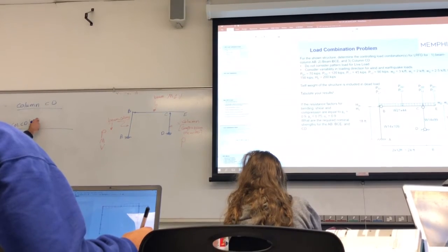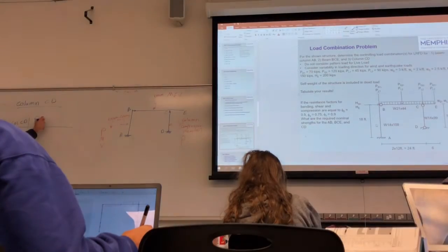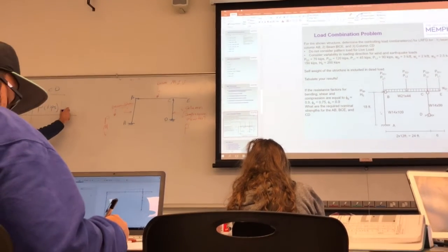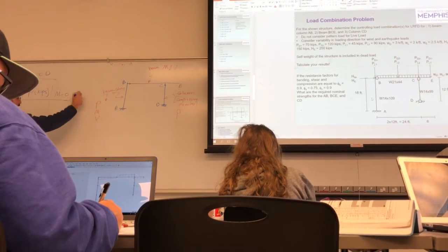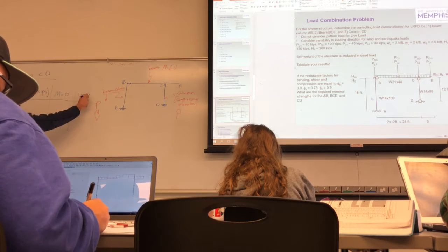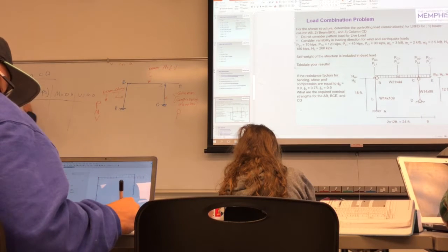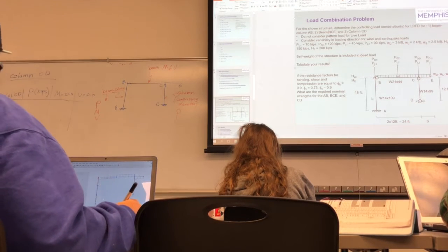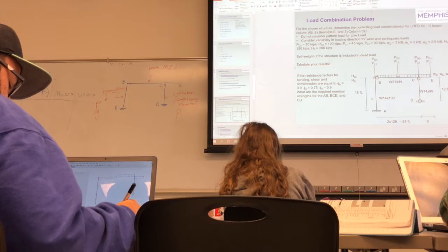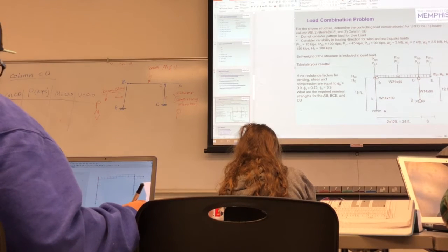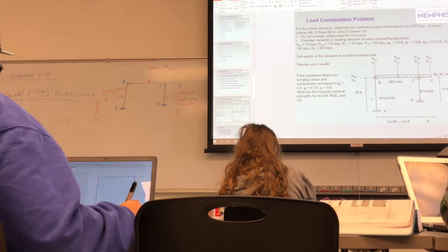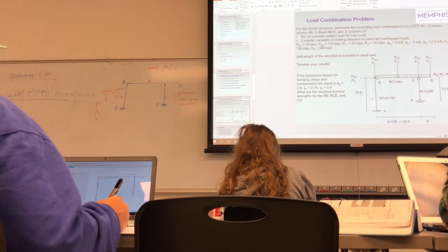and we put here that we have an axial force P in kips, and then we don't have a moment, so moment is 0, shear is 0, so we don't have to worry about it. And usually we try to tabulate our results. So what I'm doing now, actually SAP can do it for us, but I want to show you how it's done. Some of you know that SAP can do it. It takes a lot of time, but we have to learn how to do it before we let SAP do it.